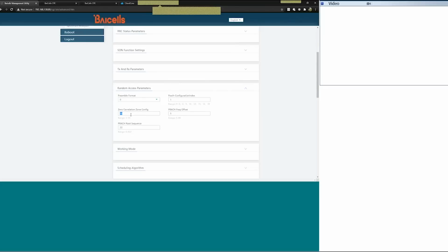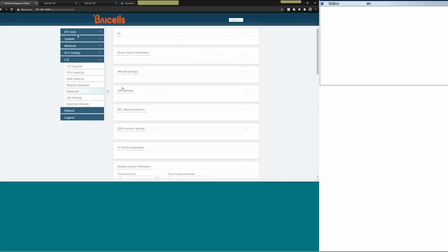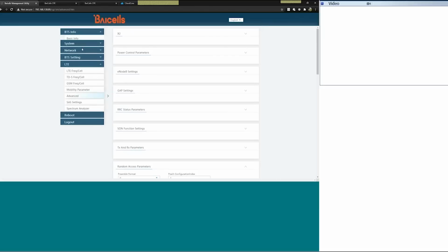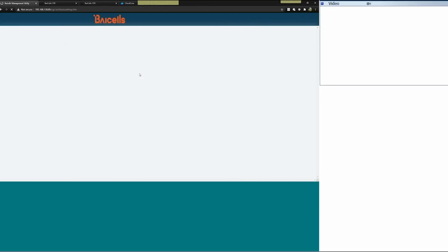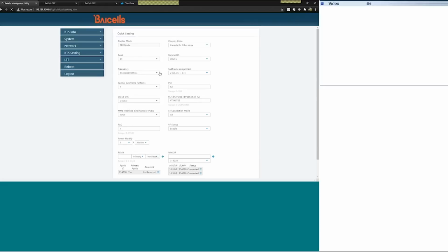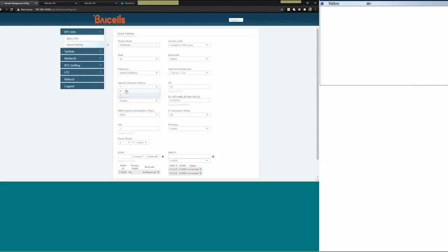The NCS, I think, is also kind of a guard period that is set a little bit longer, but the biggest impact as far as it pertains to throughput is going to be the special subframe pattern, because the guard period gets changed here. So if we go to 7 to 5 here, your downlink will be impacted for sure, because if we look at a special, let me see if I open up another page here.